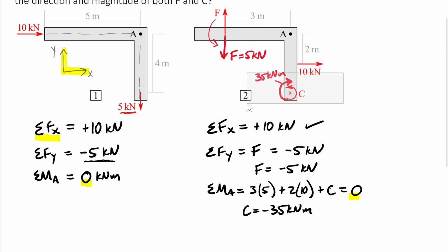I could simulate that here. Essentially I'm just saying that I could move it up around point A, over at F. It wouldn't really matter where I put it. It's still going to have the same external effect on our body. So hopefully that brings together these ideas of equivalency and also being able to find resultants, bringing those into the concept of statically equivalent systems.